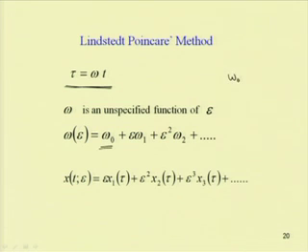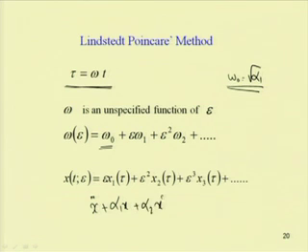So omega 0 equals root over alpha 1, where alpha 1 is the coefficient of the linear term in the governing equation. Taking x(t, epsilon) equal to epsilon x 1(tau) plus epsilon square x 2(tau) plus epsilon cube x 3(tau), and substituting in the equation x double dot plus alpha 1 x plus alpha 2 x square plus alpha 3 x cube equal to 0,